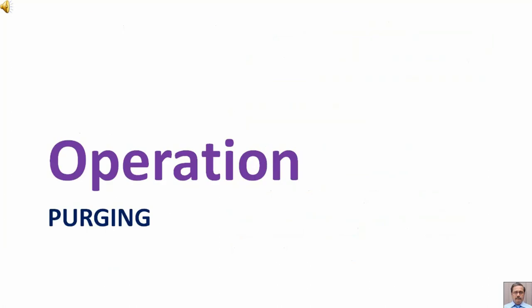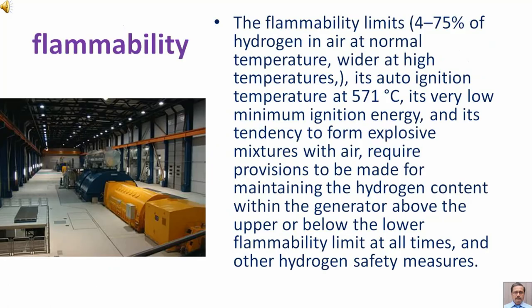Operation sub-issue: purging. The flammability limits are 4 to 75% of hydrogen in air at normal temperature, wider at higher temperatures.